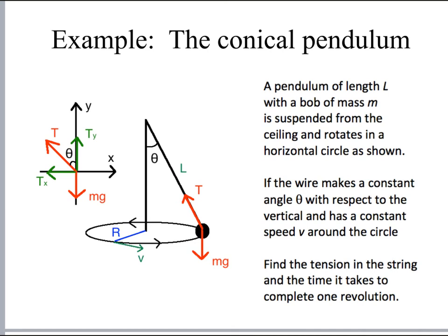Remember free body diagrams? That's where you take the forces acting on an object and you break them into x and y components isolated. And so our tension is going to break into a y component of the tension and an x component of the tension. And if this is the angle theta, if I draw this up here, that also would be the angle theta. So that's why you can see that that's going to be theta there. And so we can now apply the sum of the forces in the y direction, which would be those two forces, and the sum of the forces in the x direction, which would be that force.